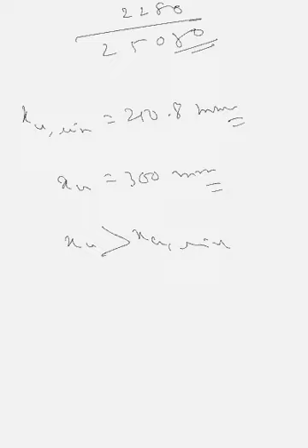Okay, now what happens in the over reinforced section? Let's understand the behavior. In over reinforced beam, the steel percentage is high. Steel does not yield before the concrete crushes. Concrete reaches ultimate strain first and crushing of concrete happens suddenly. And this type of failure is brittle. And the brittle failure is very dangerous because there is no warning, no large deflection and sudden collapse. So we always avoid the over reinforced sections in design.